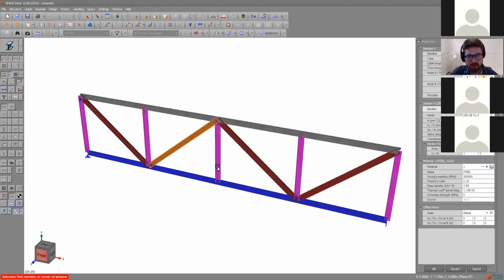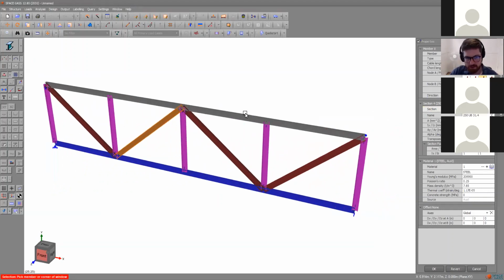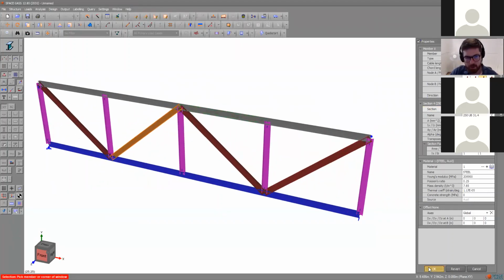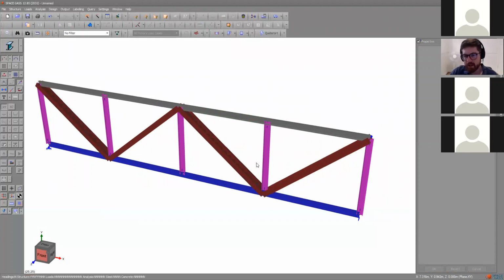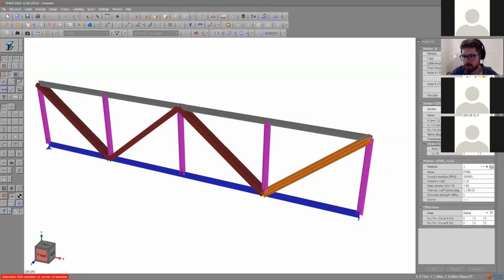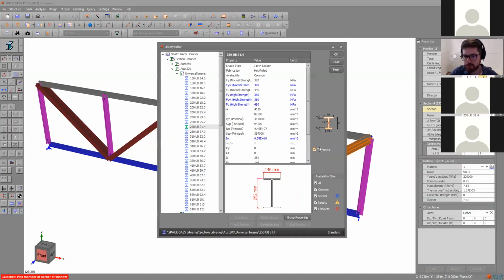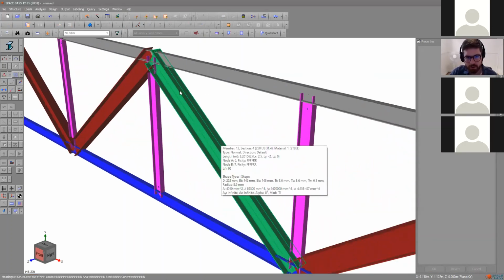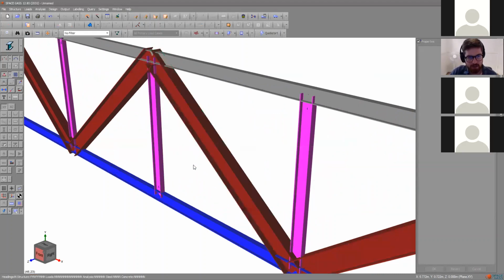And typically it's at 0 or 90 degrees, the major or minor principal axis, and your transposition tool allows you to specify that. If you look closely at Iy and Iz, it will swap those two back and forward. And in 3D, it will then swap the correct orientation to allow you a more intuitive check of the system.